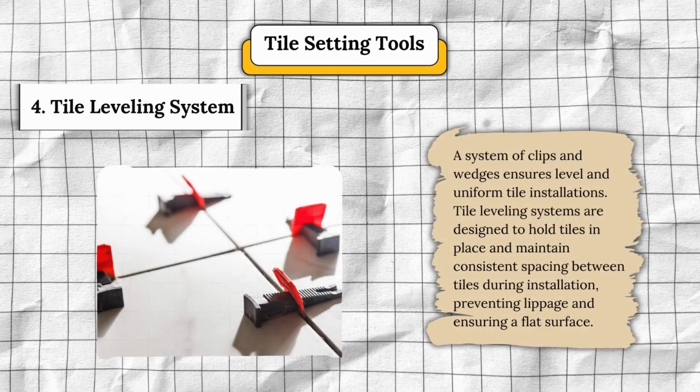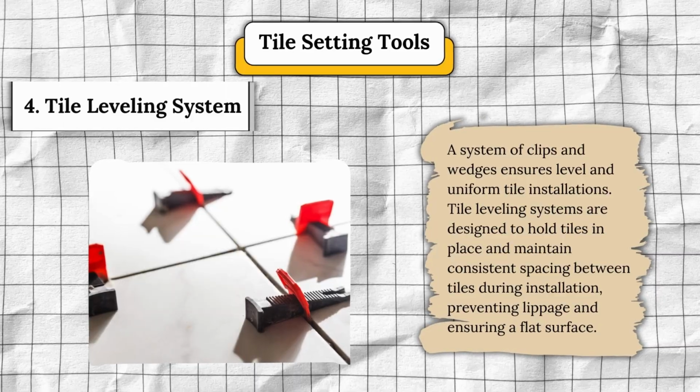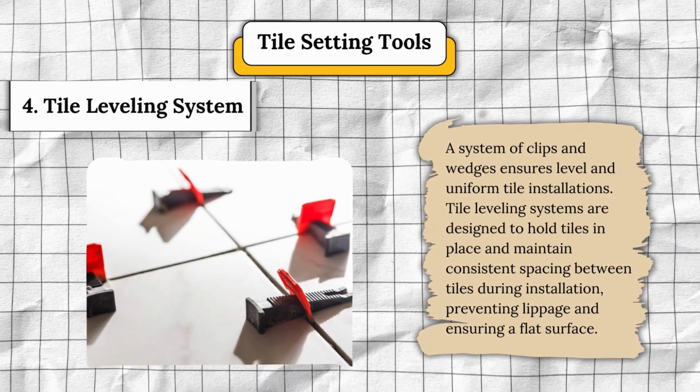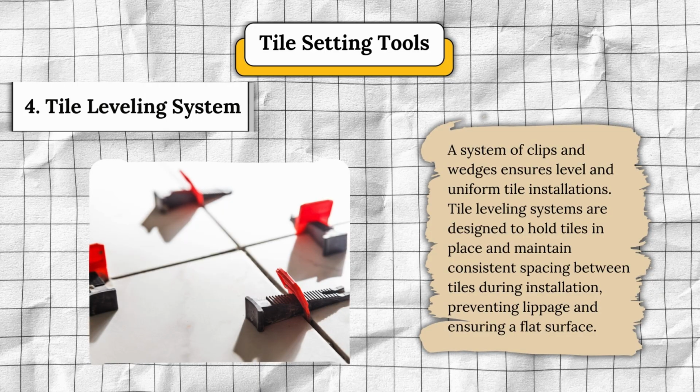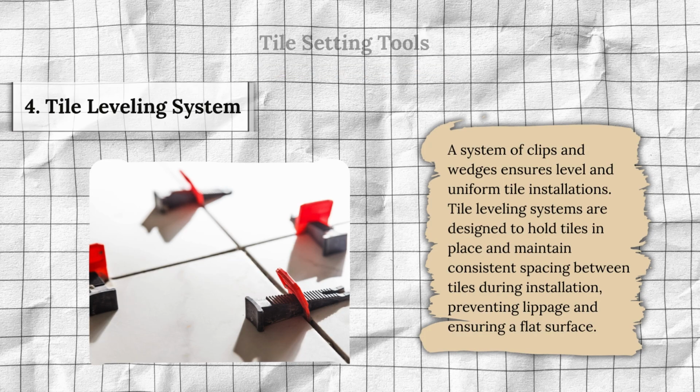Number 4. Tile leveling system. A system of clips and wedges ensures level and uniform tile installations. Tile leveling systems are designed to hold tiles in place and maintain consistent spacing between tiles during installation, preventing lippage and ensuring a flat surface.